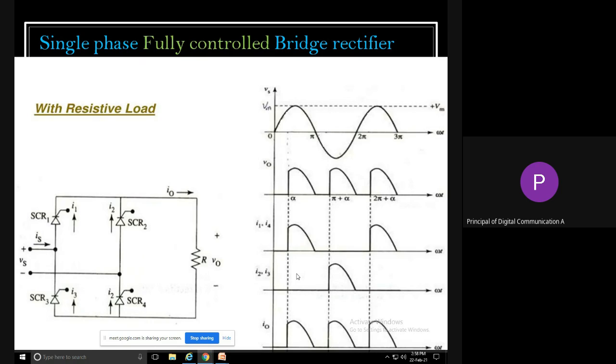So you might be aware that this is a setup for a bridge rectifier. Two diodes, or the two SCRs here, are going to work simultaneously, and the other two will be in an off condition. We assume this is the position they have given for the positive half cycle, that is, the upper terminal is positive and the lower terminal is negative. With this we can see which SCR becomes forward biased and which goes into reverse bias.